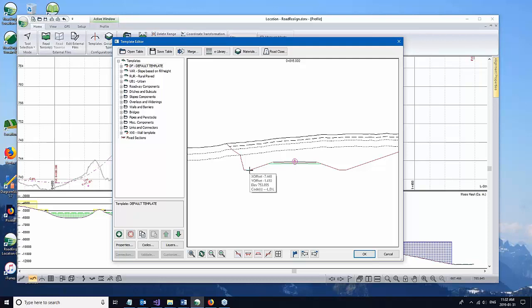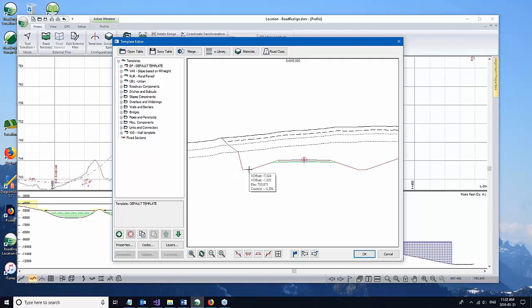Some standard point codes that come with our eLibrary are ditch inside left, DIL, DOL. That's another common one. Points can have more than one point code, but some of these are standard. A very common one is REL. So those point codes can be reported in various ways.